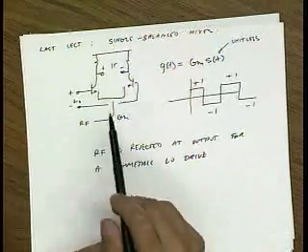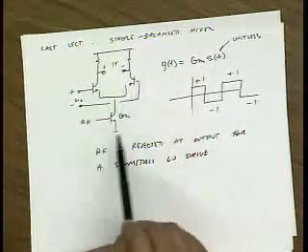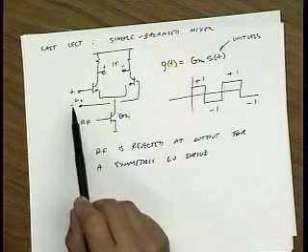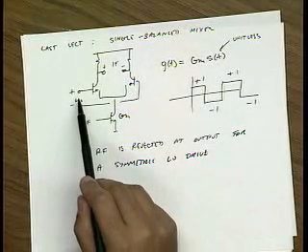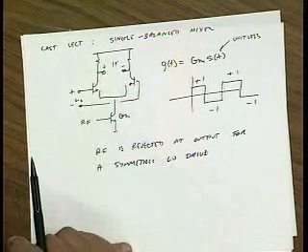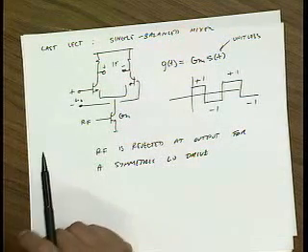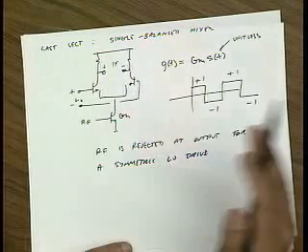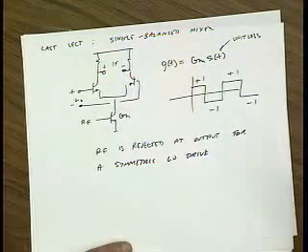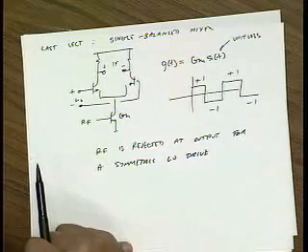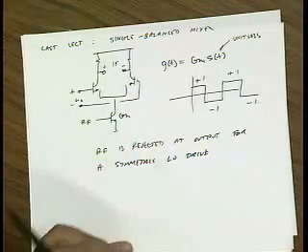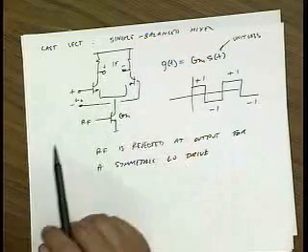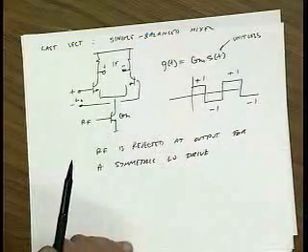What's also interesting is if you go and basically plot the noise figure of, let's say, this mixer as a function of the LO, you'll find that the larger you make the LO, the lower the noise figure. Okay? And initially that might not be very intuitive because you might think the larger the LO, the more harmonics I have, and so the more noise folding I would get, right? Which is true, but remember, as you increase the LO, you also get more conversion gain. So perhaps those two things could cancel out.